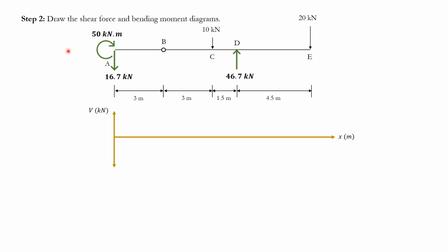That's the usefulness of moment area theorems. Otherwise, moment area theorem is not really convenient for us to use. That's why most of the questions that you see will have concentrated forces like this. So drawing the shear force diagram also is not really a big deal. It shouldn't take that much time. So that's why I do it here. But for more complicated problems, absolutely, I would say forget about the shear force diagram. Just go to the moment diagram directly.